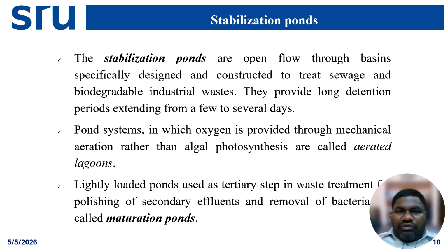So coming to the next biological or secondary treatment, which will be stabilization ponds. Stabilization ponds are open flow-through basins, specifically designed and constructed to treat sewage and biodegradable industrial waste. They provide long detention periods extending from a few to several days.